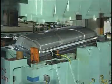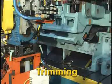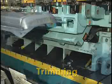Mild steel generally separates when approximately 1/3 of the stock thickness has been penetrated. However, when harder materials are die cut, penetration by the punch may be less than 1/3 the material thickness, and softer materials may require almost full punch penetration before fracture occurs. After a part has been formed, a trimming die is utilized to remove the excess scrap metal from the workpiece.